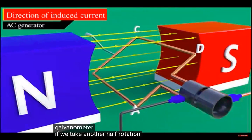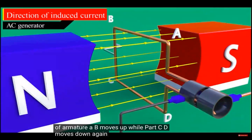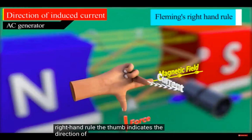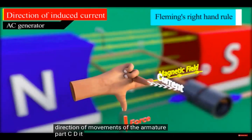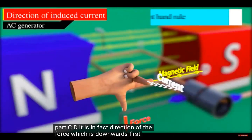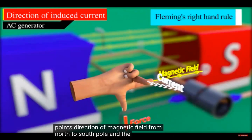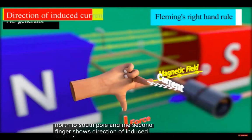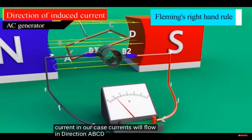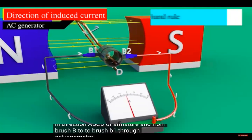If we take another half rotation, part of armature AB moves up while part CD moves down. Again, according to Fleming's right-hand rule, the thumb indicates the direction of movement of the armature part CD. It is in fact direction of the force, which is downwards. First finger points direction of magnetic field from north to south pole, and the second finger shows direction of induced current. In our case, current will flow in direction ABCD of armature and from brush B2 to brush B1 through galvanometer.